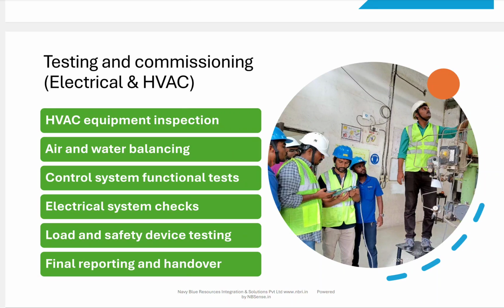Then the electrical system check. What is the startup facility, and how to make a startup? Startup means what is the startup protocol. Initially they have to take permission, then put a tag, get access, and start with a particular button. So we need to check whether the site persons are aware of the startup sequence or not.